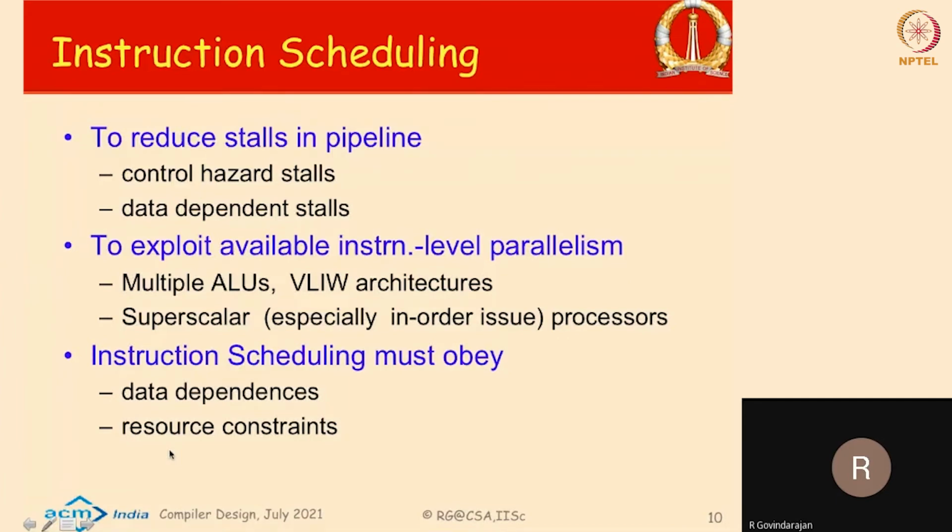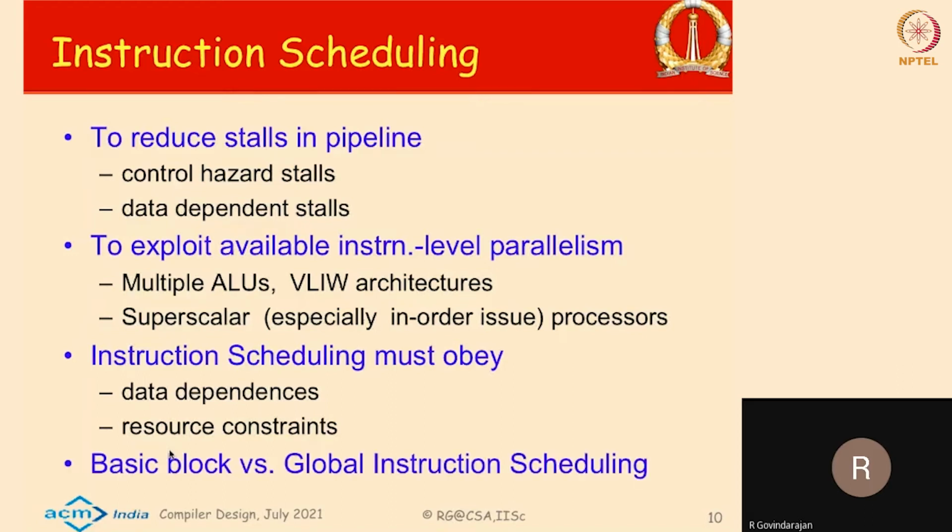We saw in our VLIW schedule exactly one load or store instruction, one floating point add instruction, and then maybe one integer and one multiply instruction in every cycle, right? Because that essentially is to meet the resource constraint of the architecture.